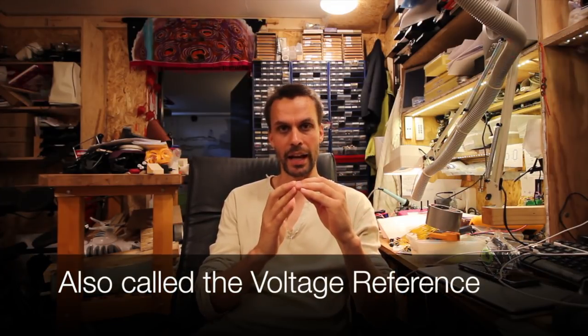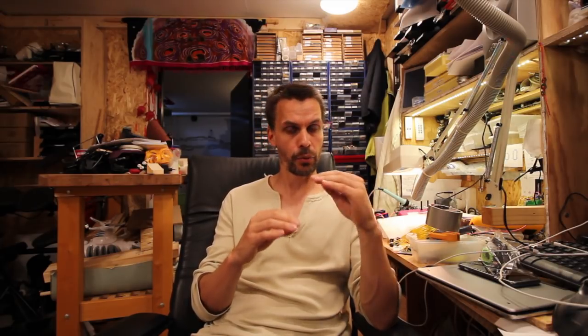But what an OpAmp comparator is, as the name implies, it compares the two inputs, the inverted input and the non-inverted input. On one of the inputs you have a threshold value, let's call it that, which you set with a voltage divider. When you compare the other input to the threshold value, if it is below that threshold value, then the output of that OpAmp will be negative voltage, if you have a plus minus OpAmp. If it is above the threshold value, it will be positive voltage.